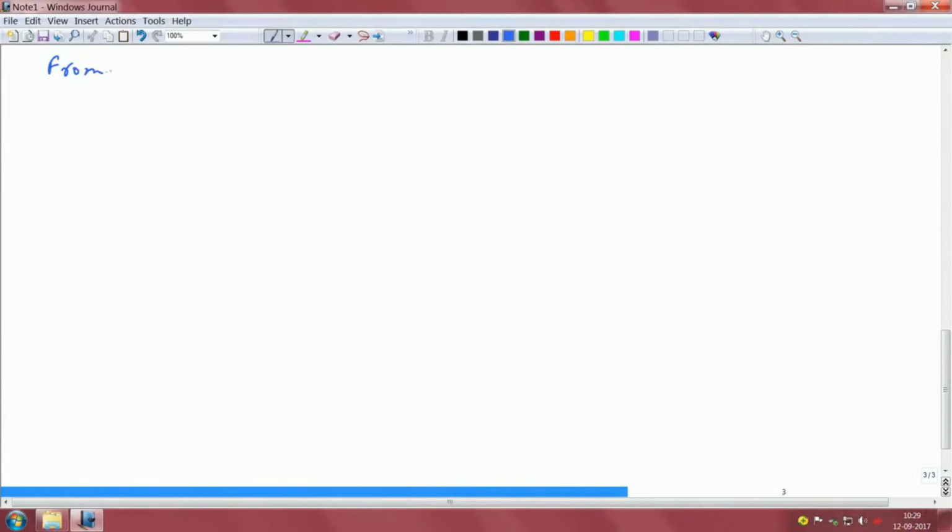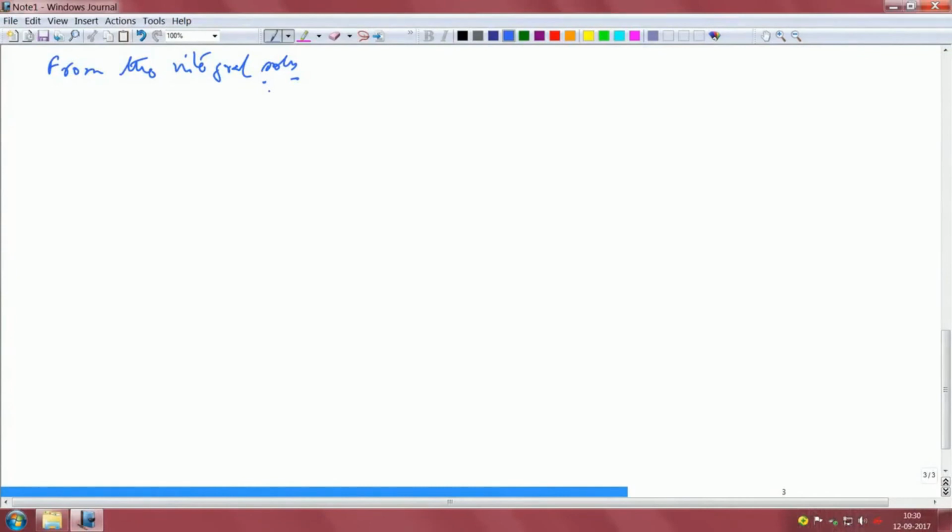Now, from the integral formulation we can try to extract the same thing, because this was done rather heuristically. We just took the scaling from the Blasius solution and applied it here, which is strictly not the correct thing to do, but we got away because this can be constituted as two parallel plates. One plate is at the top, one plate is at the bottom. So, you can consider them as two parallel plates, kind of independent with respect to each other. Now, from the integral formulation, we can apply it directly.